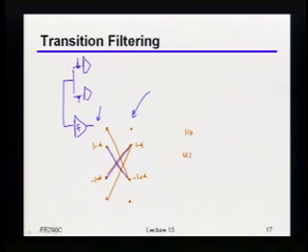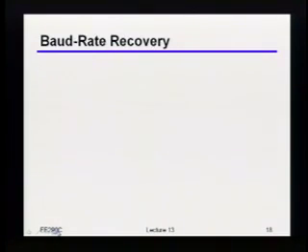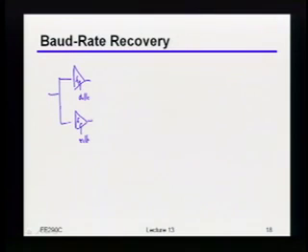Okay, so there's one last thing that I want to mention just because it's kind of interesting in the context of clock and data recovery. Originally, when we started everything out on clock and data recovery, I said that the most traditional way people do things is they have one comparator, which let's say they call the data clock, and then a second comparator, which they call the edge clock. So essentially we're 2x oversampling the data.